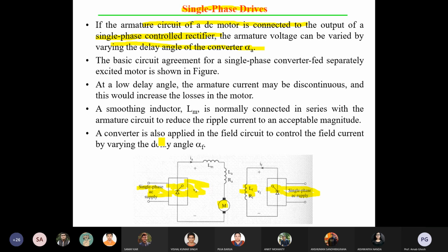So in that AND gate, what happens? You know the configuration: 0 into 1, or 1 into 0, the output will be 0. It is a multiplication type of configuration. Only when both are 1 will you get 1. If any of them is 0, the output will be 0. So when you mix in that high frequency signal with the AND gate, that is how you are mixing the signal.